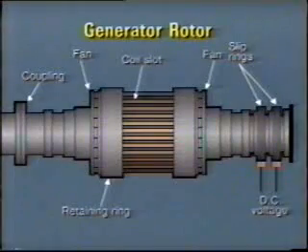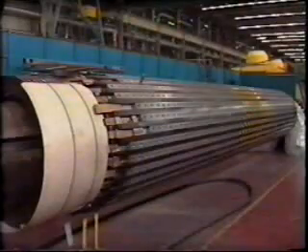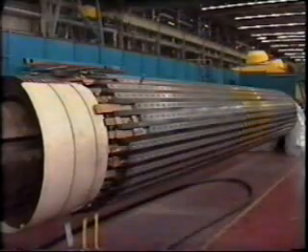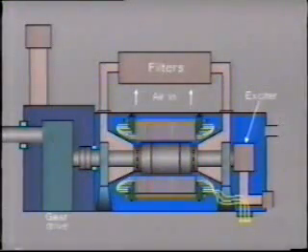As the rotor spins, the fans provide the moving force to circulate the cooling air through the rotor and stator core. Cooling ducts are often built into the rotor and stator core to allow passage of cooling air. This diagram shows a typical arrangement. Air is drawn in from atmosphere and passed through filters to remove any particles of dust or other contaminants.